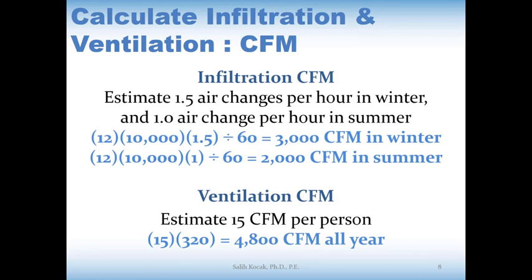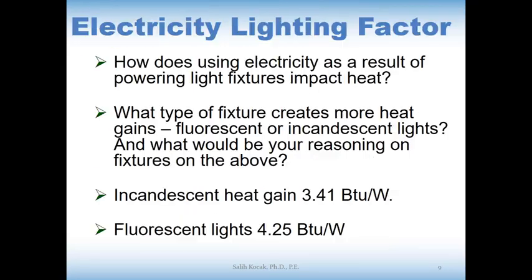So always you guys are going to be using the ventilation in that case, since this is the ventilation case. Regardless, we are calculating infiltration and the ventilation, and we are using the larger one for winter and the summer cases. Okay, so let's keep going. We have so many slides to cover in this class.